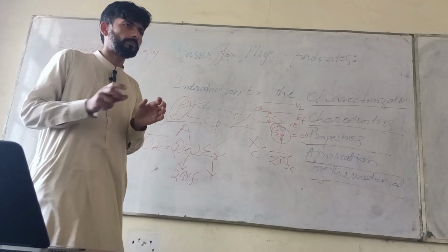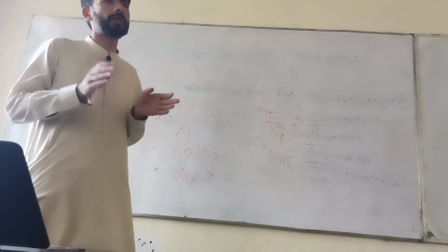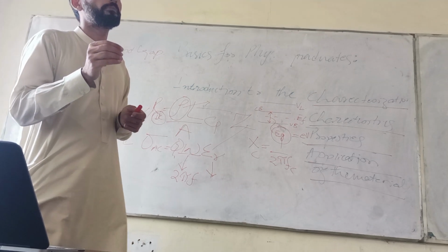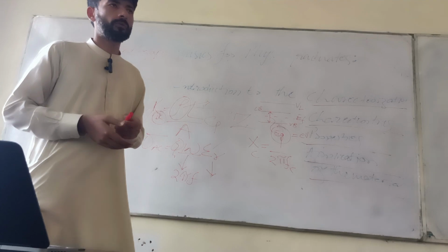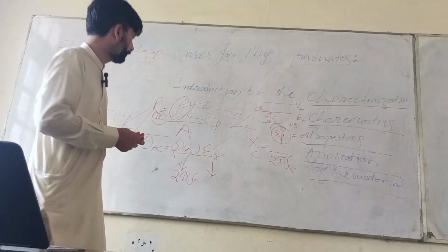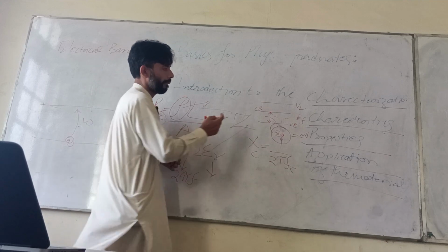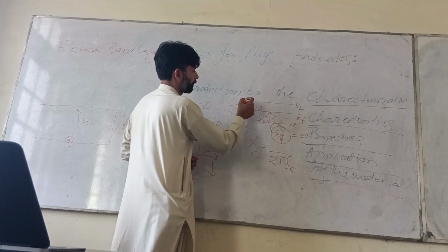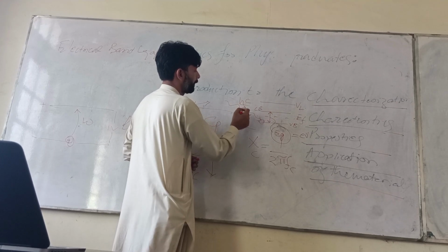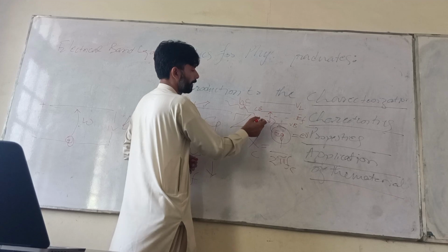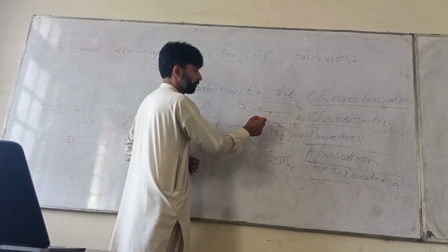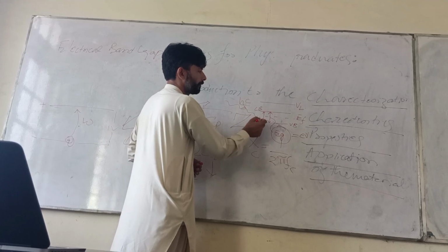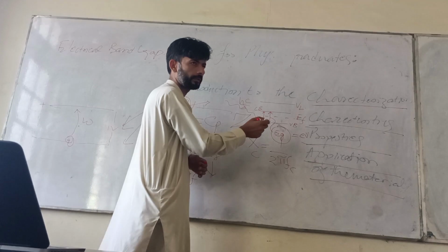Almost, the electrical and optical band gaps are near to each other, but the electrical band gap is a few electron volts above the optical band gap. In the optical band gap, we usually provide the energy, by wavelength lambda, to the electron in the form of light, and it jumps from the valence band into the conduction band.